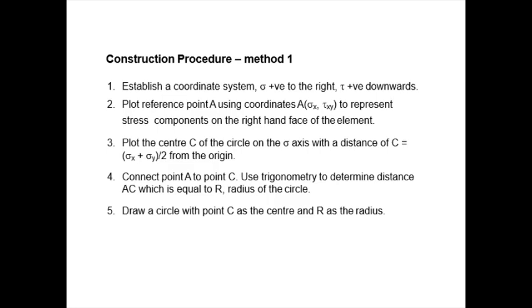So if you draw using a graph paper, you use accurate axes, accurate lines. So you have to use drawing tools to aid you. And also you use the scales for X and Y axis, or the normal stress and the shear stress axis. You use the same scale for both axes. So you need to determine where the axes are, right?